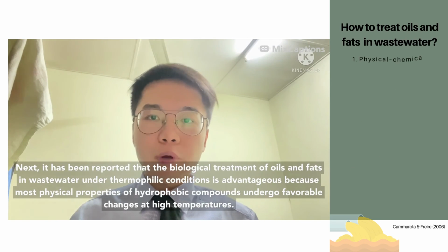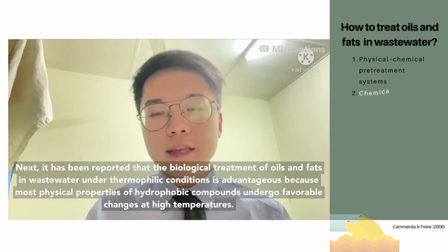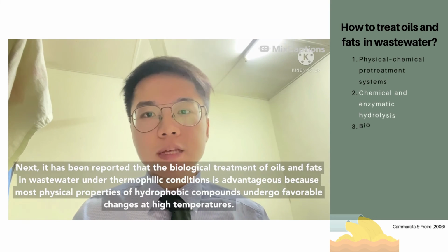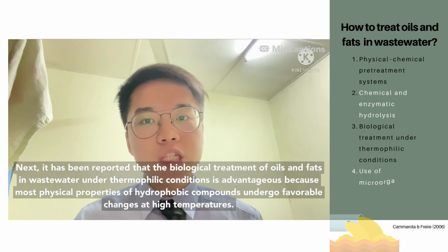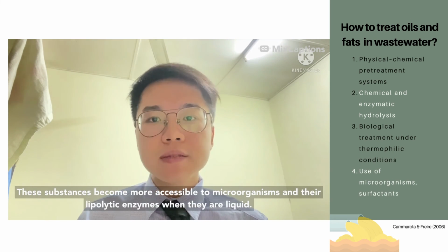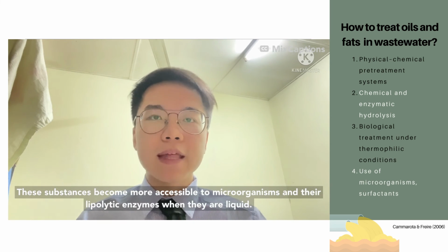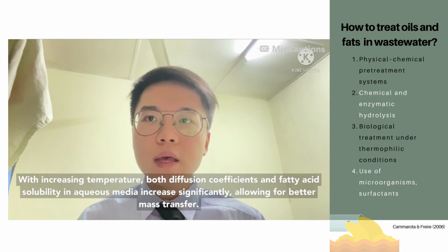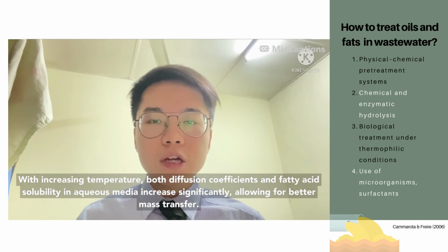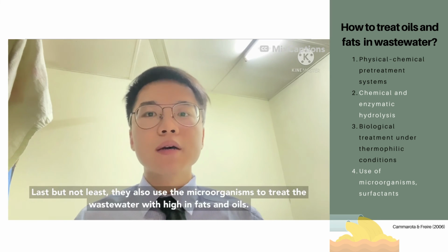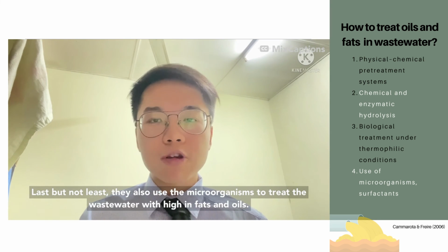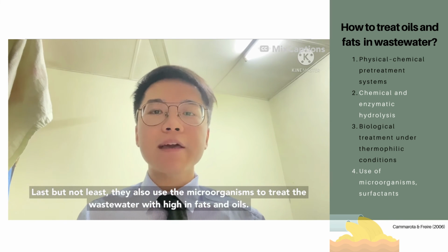Next, it has been reported that the biological treatment of oils and fat in wastewater under thermophilic conditions is advantageous because most physical properties of the hydrophobic compounds undergo favorable changes at high temperatures. These substances become more accessible to microorganisms and their lipolytic enzymes when they are liquid. With increasing temperature, both the diffusion coefficient and fatty acid solubility in the aqueous media increase significantly, thus allowing for better mass transfer.